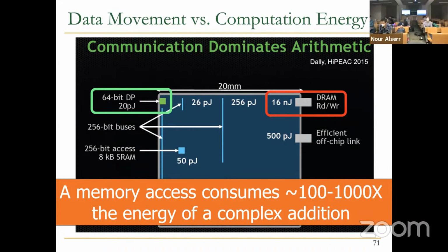Now, does it get exposed to software is the major question in RowHammer. And as far as I know, not yet. So flash memory has a lot of mechanisms to overcome the read disturbance. So it's very hard to exploit those read disturbance bit flips in flash memory. People have shown that this exists in emerging memory technology like STT-MRAM. I think there was an ICCD paper a few years ago that shows that there are RowHammer attacks on STT-MRAM, which is an emerging memory technology, which we will talk about later on. So fundamentally, RowHammer bit flips exist, but they may not be exploitable from the software perspective.